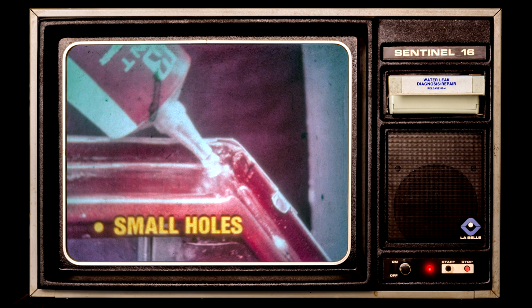Small holes can be sealed with Kent Industries Quick Leak Check or 3M's Auto Joint and Seam Sealer, Flow Grade. These are light-colored, fast-drying, flowable sealers designed for use on small joints, seams, or holes. They dry quickly to a firm, rubbery consistency and can be painted shortly after application if necessary.